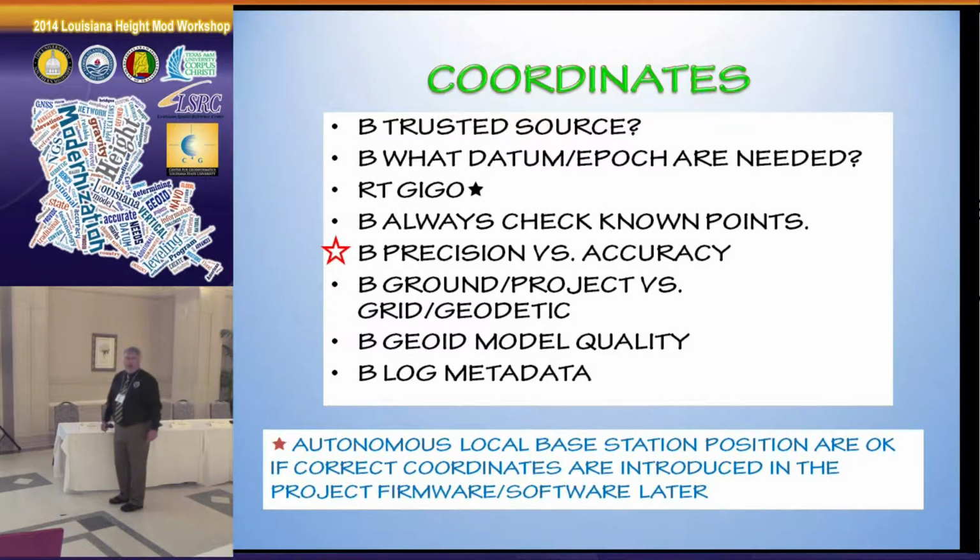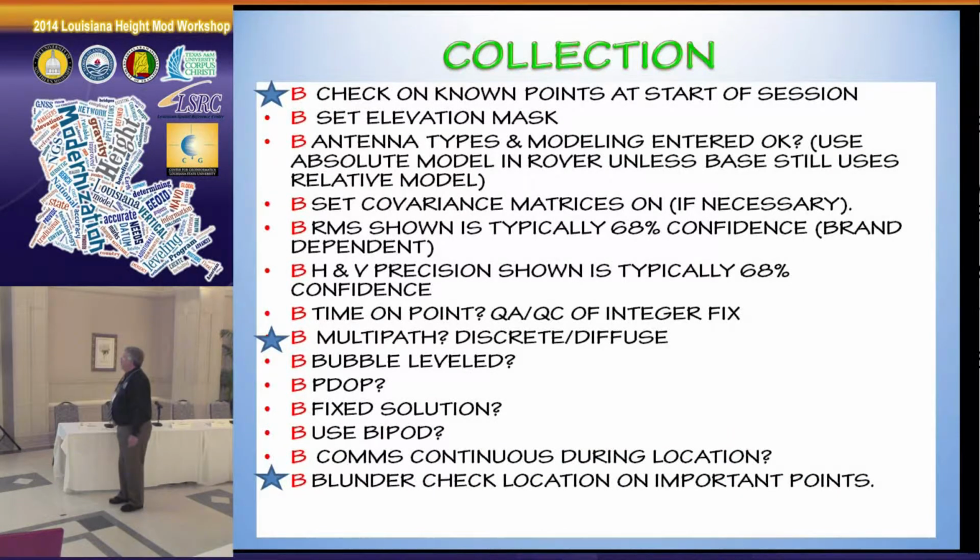Yeah, you type in a bad coordinate, everything you do from your base station will be wrong. Fortunately, you could correct it if you know you did it. Collection, the big one.